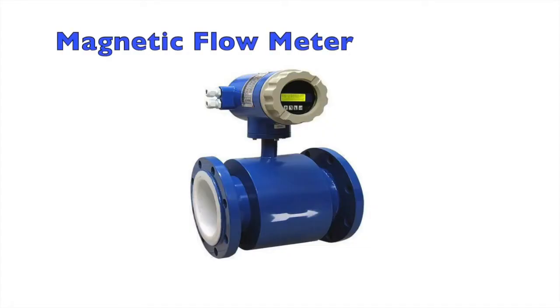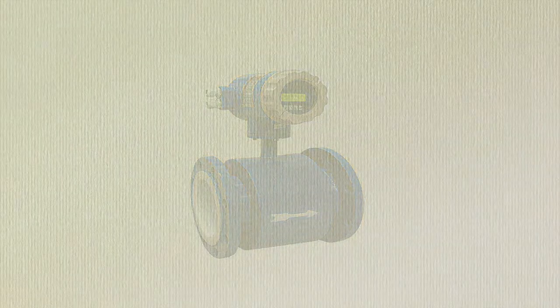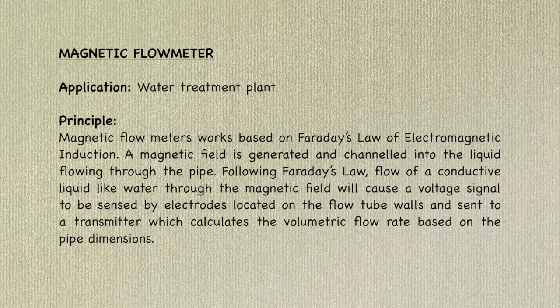Electromagnetic flow meters are volumetric flow meters, which are ideally used for wastewater applications and other applications that experience low pressure drop and with appropriate liquid conductivity required. So, magnetic flow meters work based on Faraday's law of electromagnetic induction.